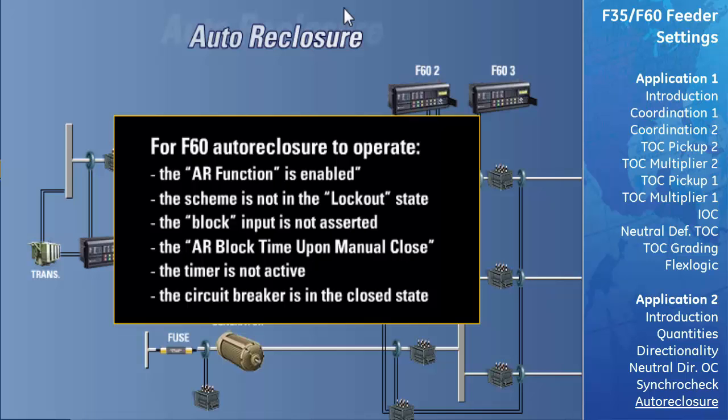The AR function is enabled. The scheme is not in the lockout state. The block input is not asserted. The AR block time upon manual close timer is not active, and the circuit breaker is in the closed state.